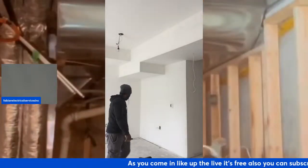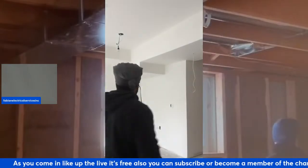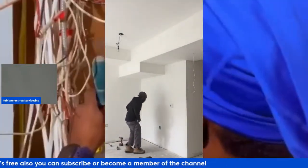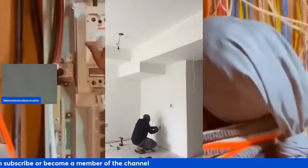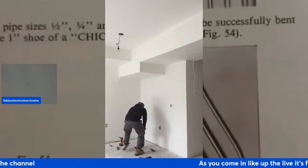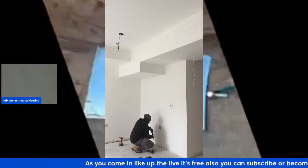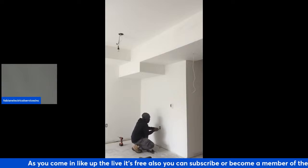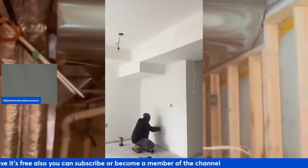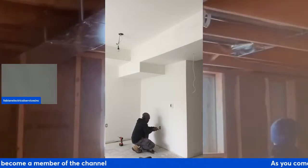Again, this room here is basically regular receptacles that are being installed. 15 amp tamper-resistant receptacles, which are going to carry again the AFCI protection, the arc fault protection. Why is it carrying that? Because the OESC 2024 states that receptacles, 15 amps, 20 amps, I believe, will carry an arc fault breaker.